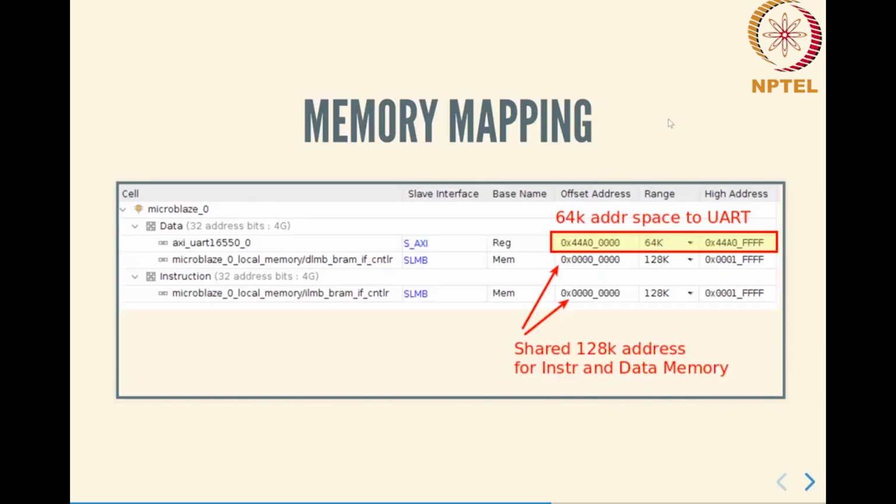Effectively, what is going to happen is if I write to any one of those addresses, the arbiter or interconnect is going to activate or wake up the UART and say, look, the processor is trying to talk to you. You need to respond based on some part of the address that the arbiter will pass on to the UART. It won't pass on the entire 32-bit address. It will only pass on whatever is required for the UART. The UART will then decode that address and decide, is the processor asking for a status? Is it asking to send a new byte out on the port? Is it asking to retrieve a byte that has already been received on the port?